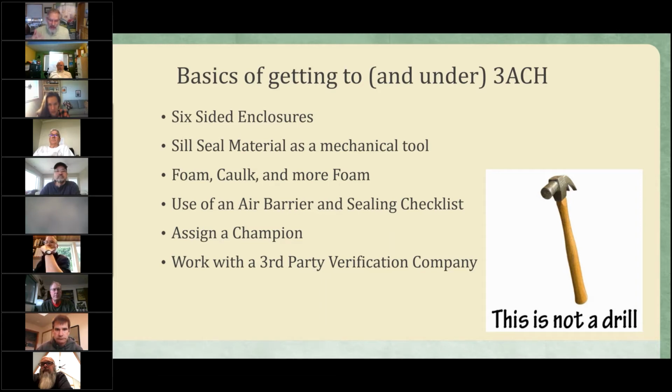So if you've got the exterior wall, the stud cavity, you're putting insulation in there, and then you put right up against it a non-rigid material or a fireplace or a shower ensemble that has not been 6-sided enclosed. If you seal that up, we can help you get to 3 ACH, and I've got some pictures here as well.